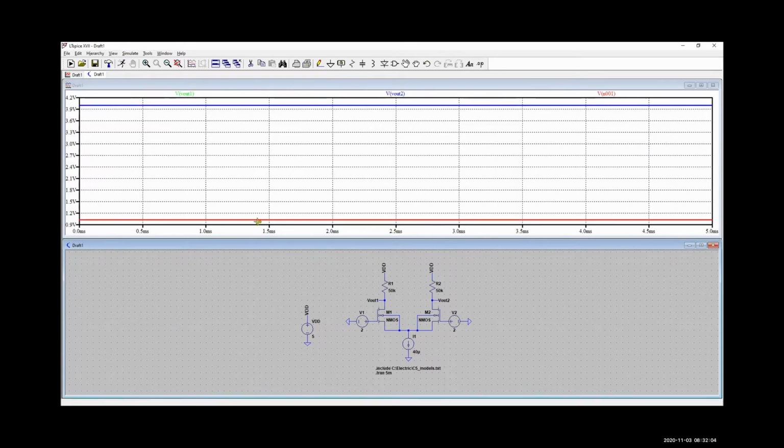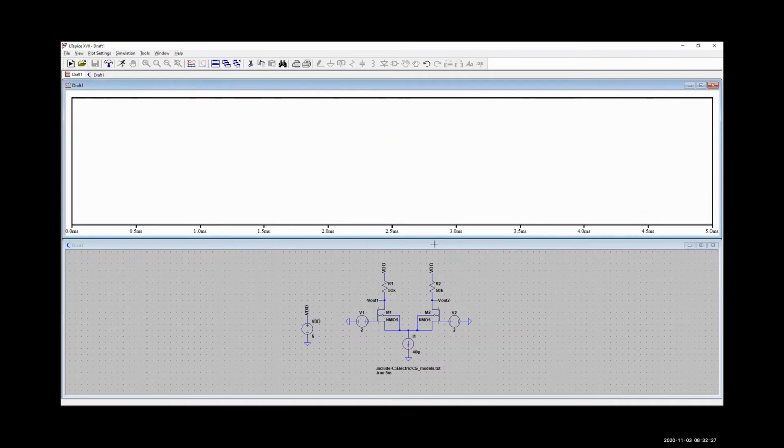Our source voltage is way down here at approximately positive 1 volt. So it's about 0.95 below this. Anyway, so we can see that our common mode signal, or whatever amount of voltage is common to both inputs, gets rejected.